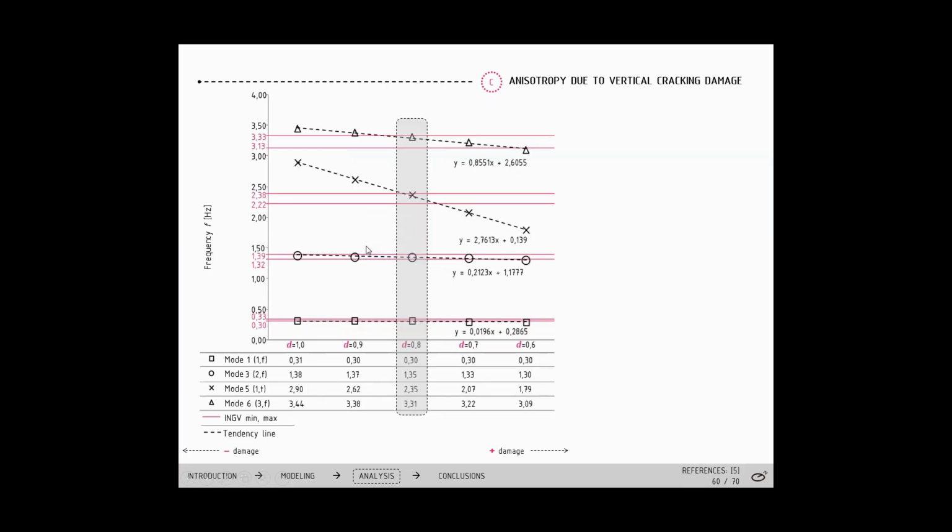So we go to Analysis and Load Analysis Command. We can delete the structural linear static here with this button, since we are interested just in the modal analysis. We check the modal analysis properties, and if everything is okay, we click Run. And once the analysis is done, you already know how to open the result files in FX+, and then you can continue doing that.